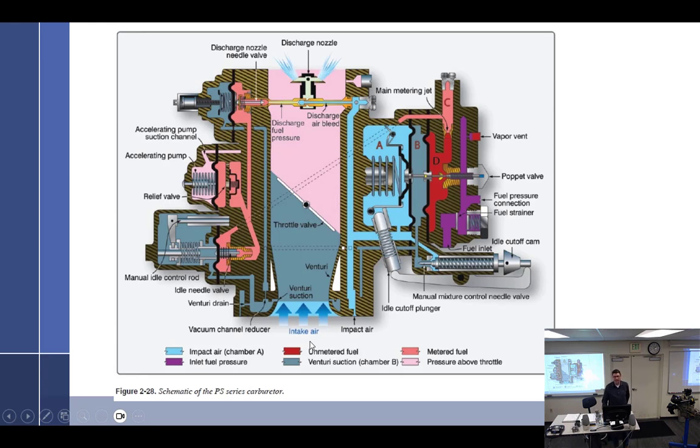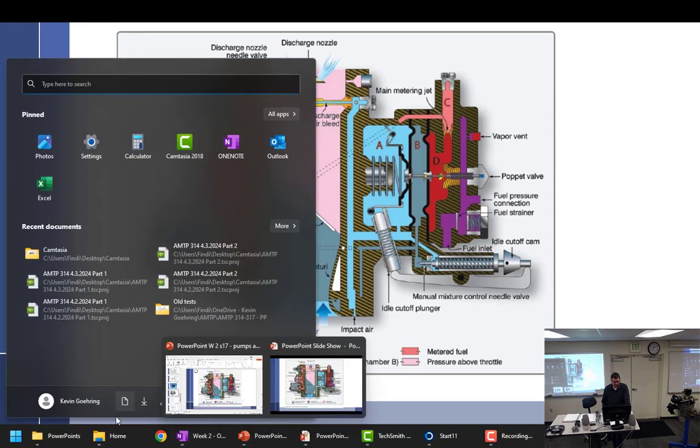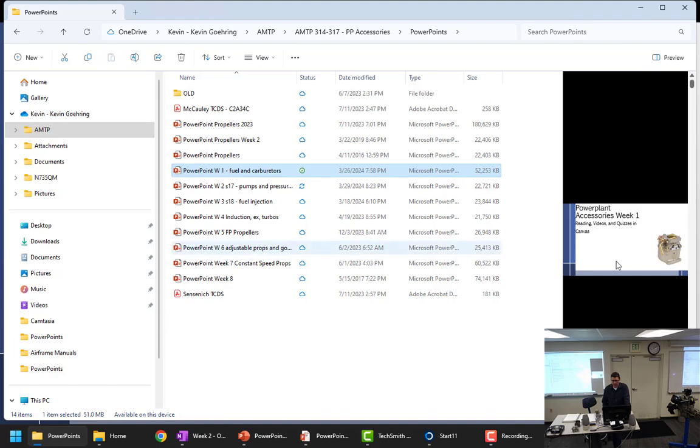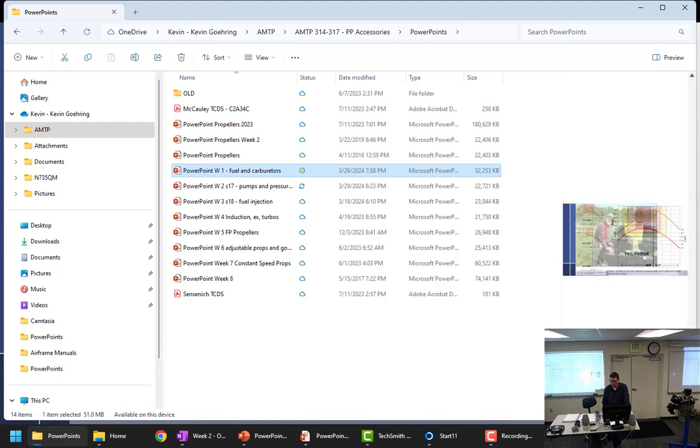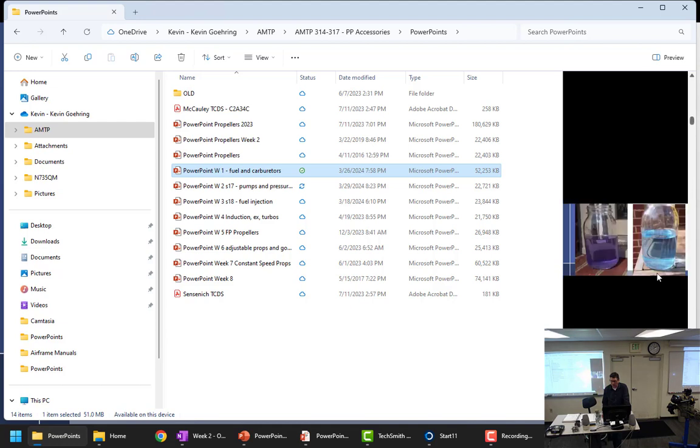Is that the problem with starting those things, as they flood? Wouldn't it pull on the throttle valve? No, it'll run off. And usually you crack the throttle anyway a little bit, so it's usually open some. If it's a downdraft, then it's going to flow down into the engine. Would that hydraulic lock you if you had too much fuel? That's what I wanted to find out. So the boost pump is providing enough force to open that, theoretically.